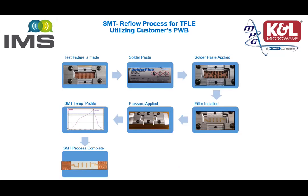Next, I would like to go over quickly the process that we do at K&L Microwave in order to satisfy a fully customized solution. We start by building a test fixture based on your PC board information. We place solder paste in different places. We install the filter.